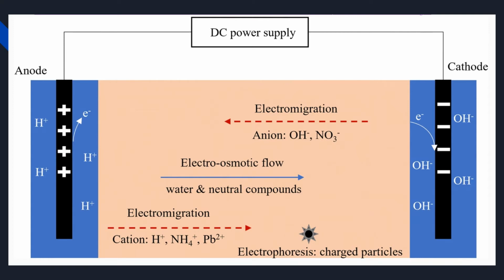However, there is another important takeaway illustrated in this diagram. Notice that surrounding the anode is an acidic front of H+, while the cathode has a basic front composed of OH-. This acid-base distribution is further useful in mobilizing metal contaminants up the cathode for further collection, removal, transport, and treatment.